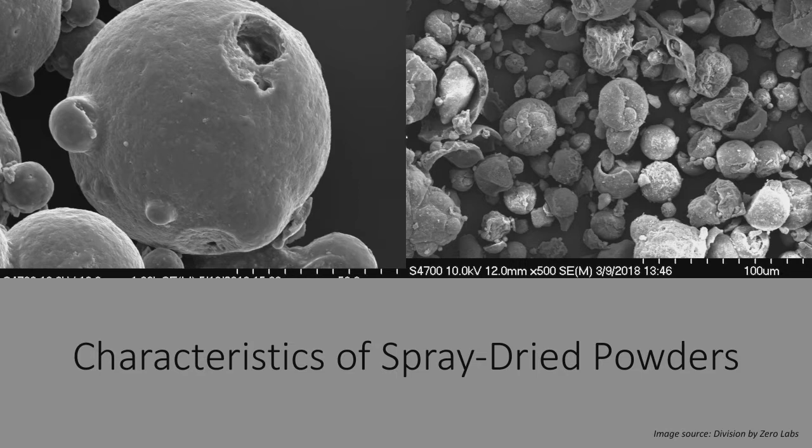But the main consequence, I guess, that I want to point out with this is the main drawback of spray drying: oftentimes the powders that they produce are so light in terms of density that it will result in poor flow characteristics. And also sometimes they'd be very hard to reconstitute back into a liquid. This is because the particles are so light that they can't even break the surface tension of water. We'll talk more about this later.